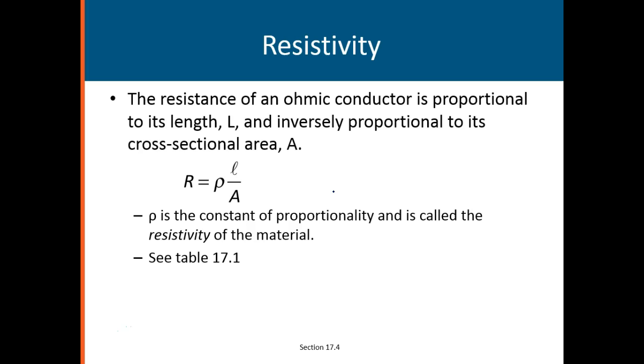Not very great. The next best conductor or lowest resistor is gold. 2.44 times 10 to the minus 8. So you see the jump between silver and copper is much less than the jump between copper and gold, which is the next best, lowest resistivity. Then from gold to the next one is aluminum, 2.82 times 10 to the minus 8. So aluminum's not a lot worse than gold. I mean, gold is a little bit better than aluminum, but not by a huge amount. Actually more than the difference between silver and copper. Those are really, really close.